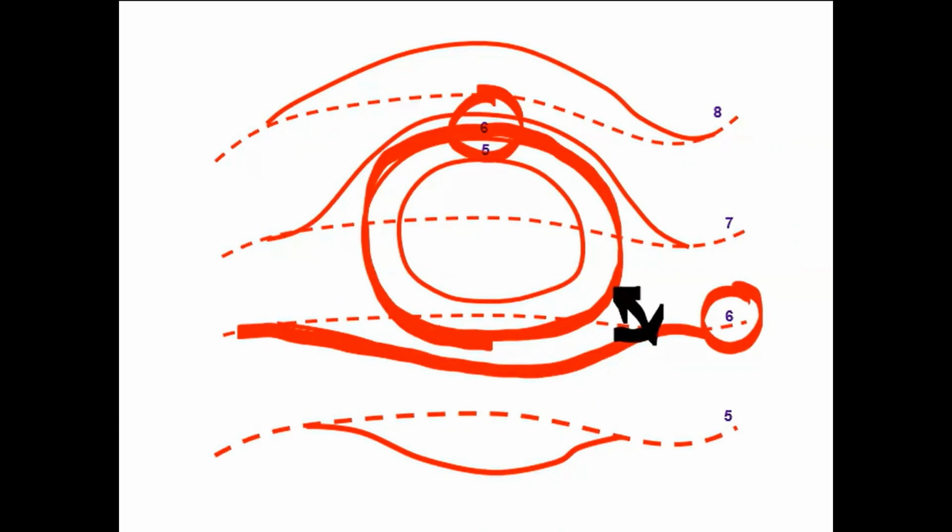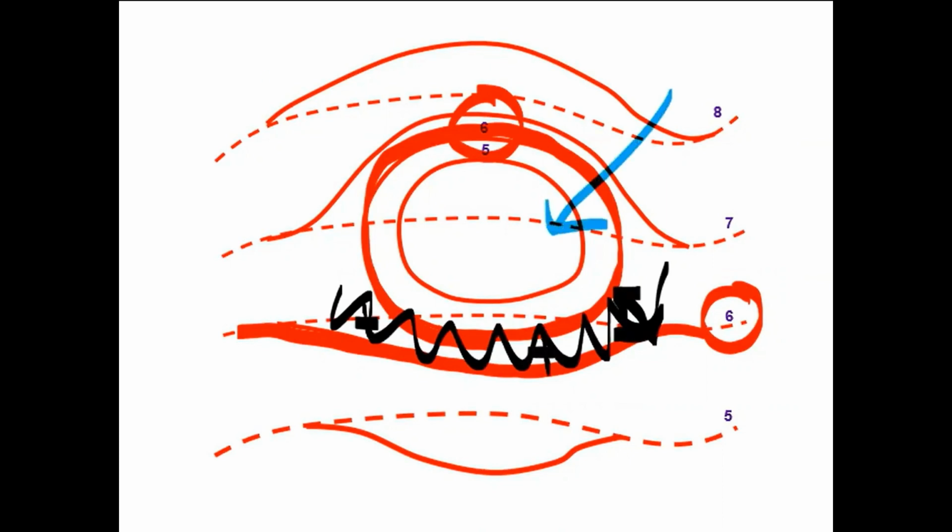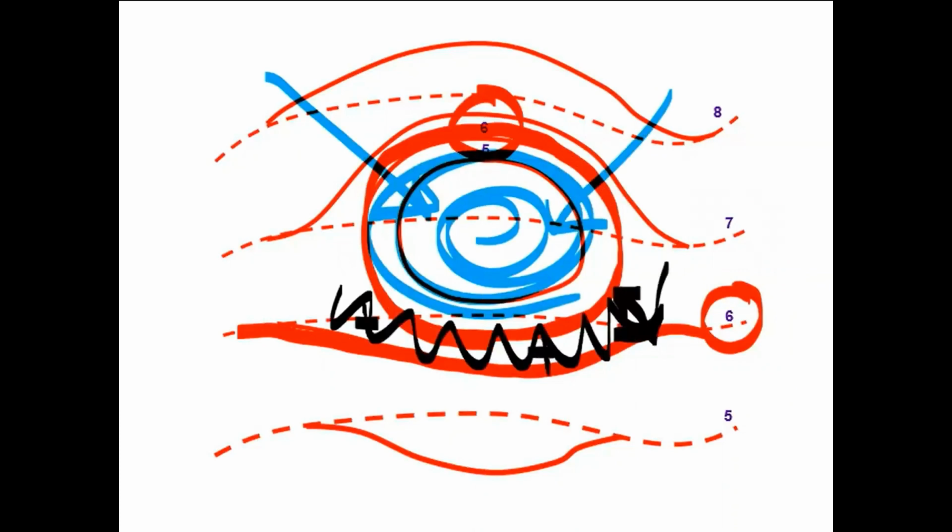The reason that we do that is that eventually we're going to need to create high points here so that, in all honesty, we're creating a berm that goes below our retaining area. Water will then flow into the retaining area. It will fill up with water, but water will not overflow down the hill because we've created a berm or a dam, if you will, right across here. We're going to talk in more detail about how we're going to specify that and also how we're going to create a raised drop inlet so that water does not overflow.